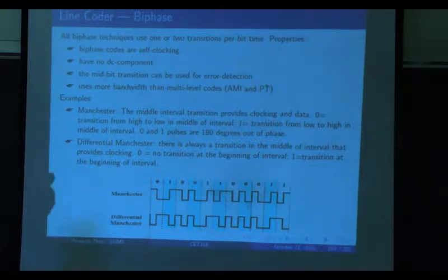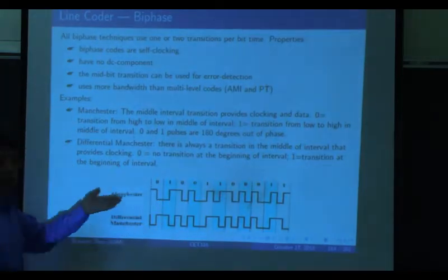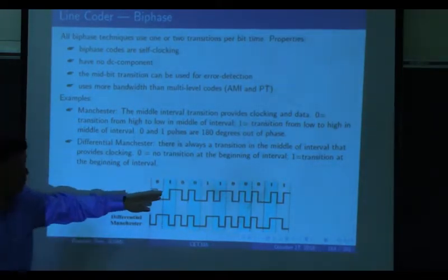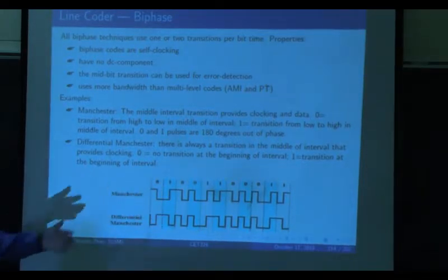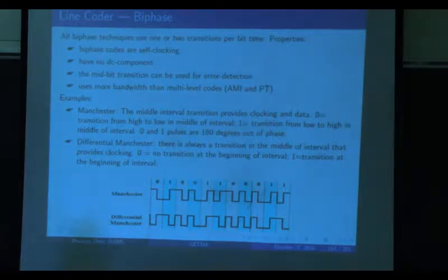how are you going to transmit wirelessly? Can you transmit the DC signal wirelessly? For a short time? For short term. You mean short range? Yeah, short range. Right? But that is not a real DC. Theoretically it still changes, it is AC. Right? You directly transmit DC. Can you transmit your 3.7 volt battery wirelessly to somewhere without any AC involved? No way, right? So DC cannot be transmitted wirelessly. If you have, for example, 1, 1, 1, 1 like this, how can you transmit this wirelessly? You cannot. But this one, we don't have any DC component, so it can be perfectly transmitted with the wireless channel. Right?